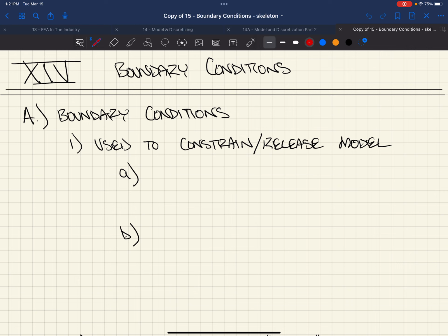We want to make sure at the same time, though, that we're constrained enough that our model is stable. And if it isn't stable, then there's some fundamental problem with our real world structure in the first place. The architect comes to you and gives you something, and you put it in the model and constrain it based on the constraints that they have. Hopefully it's intuitive to you as a structural engineer that you can see some instabilities at first glance.